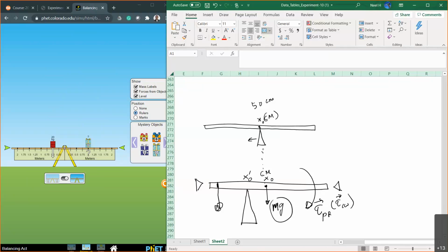If you touch the table, that vibration makes it imbalanced. It's very difficult to find the exact balance point. If you don't have the exact balance point, then our next calculation is going to be very inaccurate, so the error is going to be too high. That's why it has to be done very carefully and smoothly, then you will get the right answer.